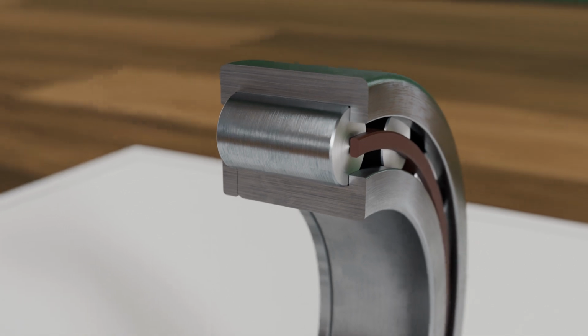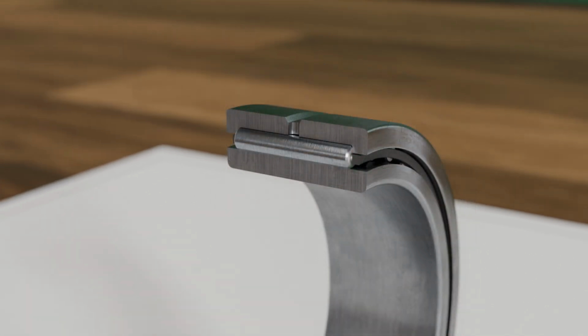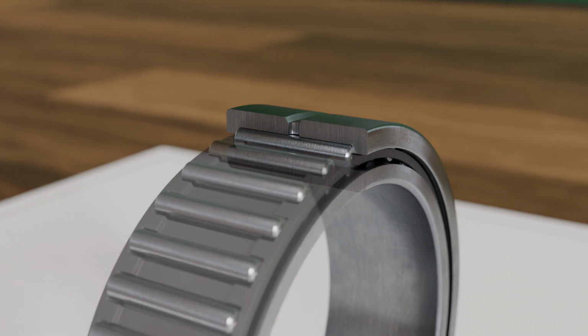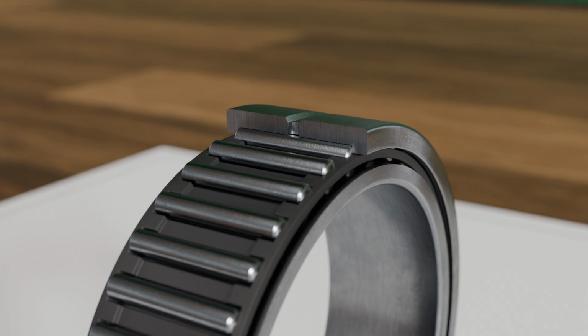A special type of roller bearing is the so-called needle bearing. The rolling elements are significantly slimmer and longer than in cylindrical roller bearings. Due to the many small rollers, needle bearings have a very high radial load capacity while being extremely compact. They are mainly used in applications with limited installation space, such as in gearboxes, joints, or small auxiliary units. However, they are not suitable for axial loads and usually require very good lubrication. Needle bearings are available in various versions.